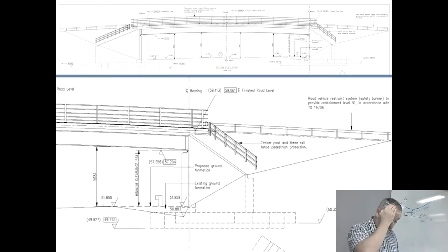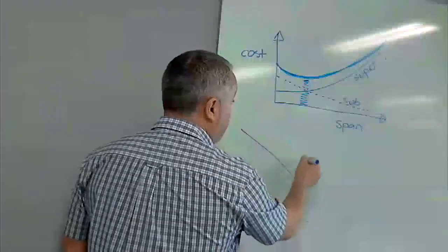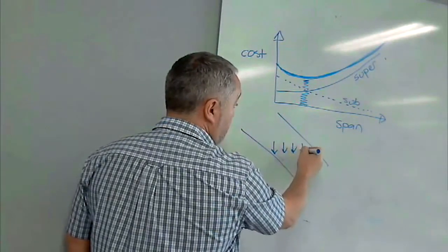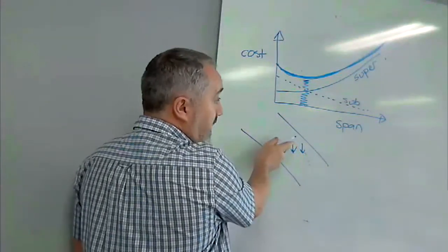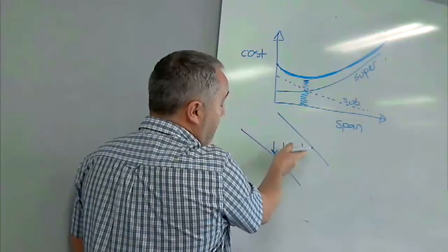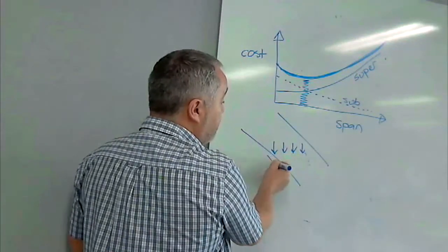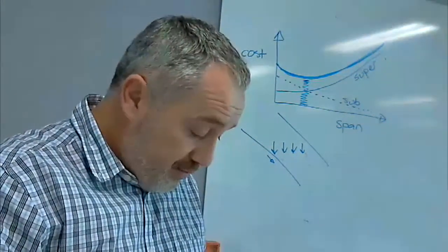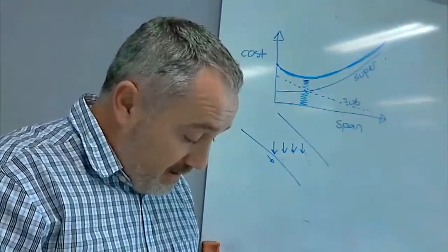But also you've got to look at knife edge load across the bridge itself when you're looking at the shear force. And you also look at a knife edge load for skidding, so a horizontal braking load.